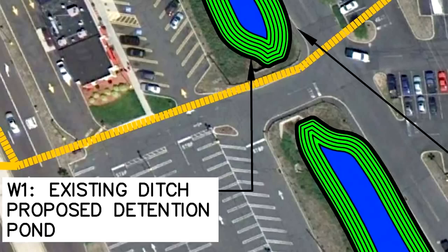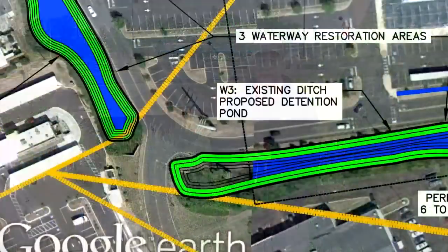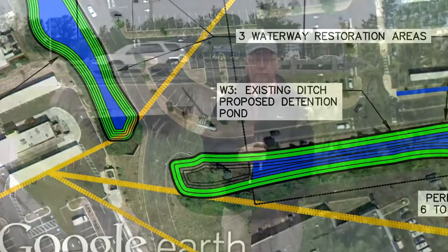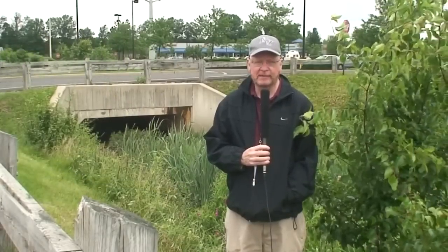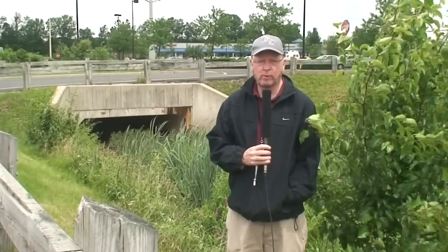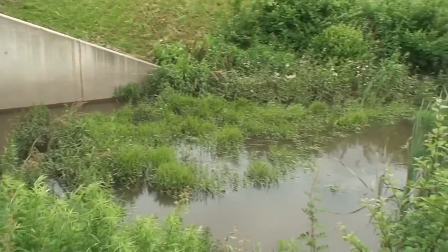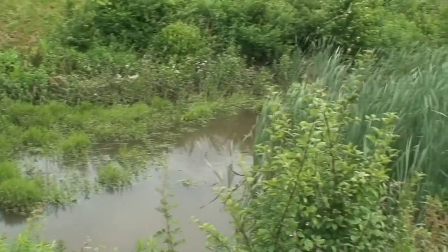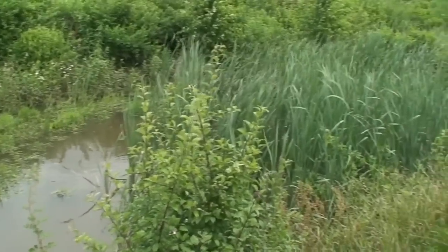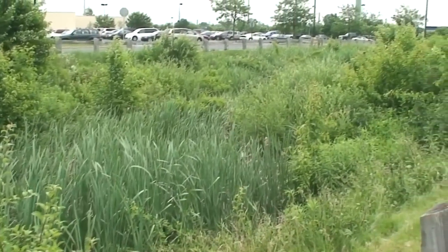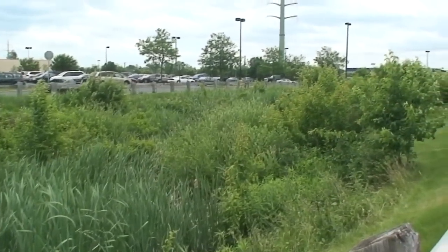These weirs will be made of stone gabion baskets which allow water to flow through them, and when water flows through a stone gabion basket, it actually provides water quality treatment with the biological processes or bacteria that live in between the stone. By slowing the water down, you give the wetland vegetation a much better opportunity to treat the stormwater. You allow the wetland vegetation to absorb more pollution being conveyed by these 3 ditches.